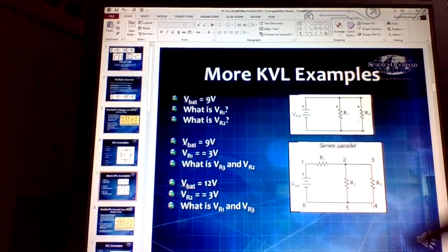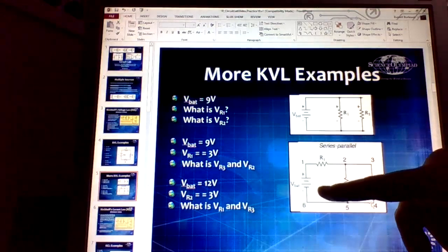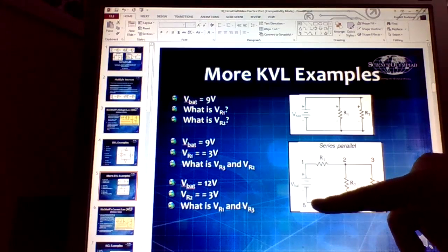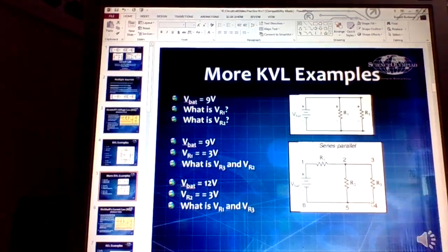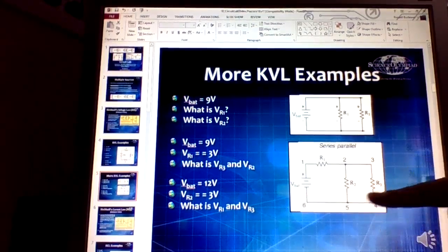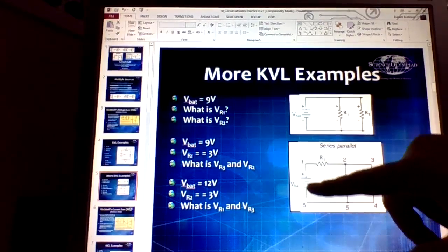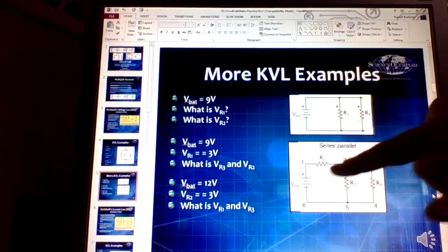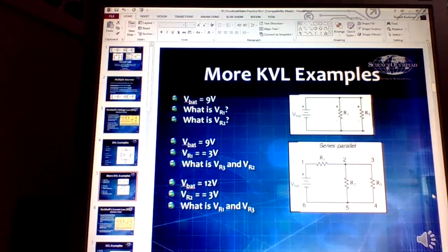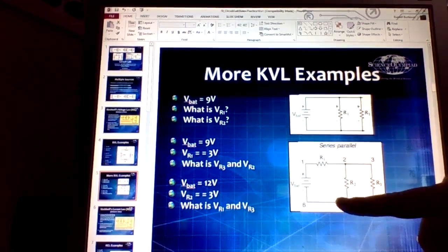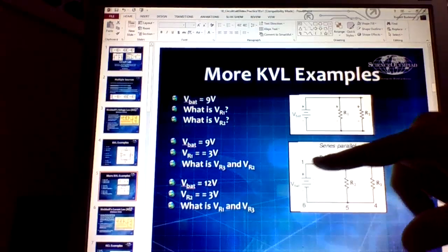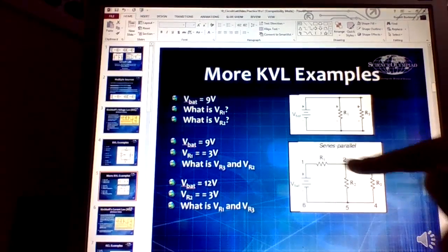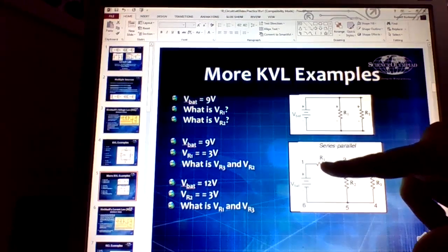Okay, and here's some more cases where a KVL would be really useful because the voltage of the battery here is equal to, if I start here, starting at 6, and 6, 5, and 4 are all equivalent. So I really only have one node right here. If I make this 0, then this right here is V battery. This is V2, which is the same as V3. So I've actually only got 3 nodes, 1, 2, and this one down here. And so the voltage of R2 and R3 is going to be the same when I do the KVL, but it's going to be split with R1.